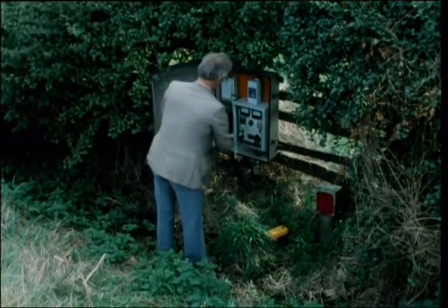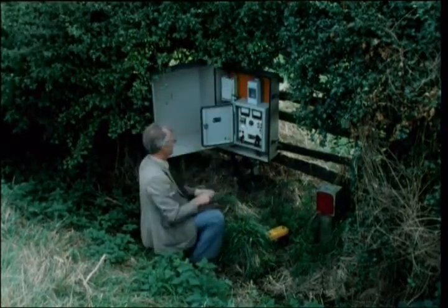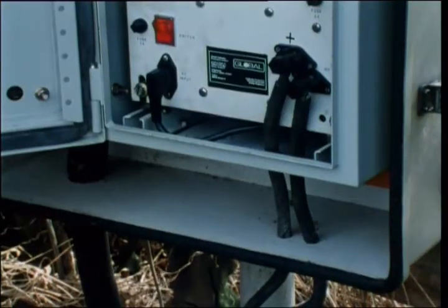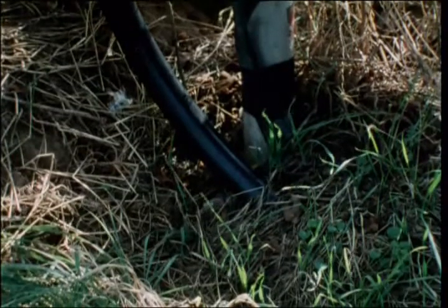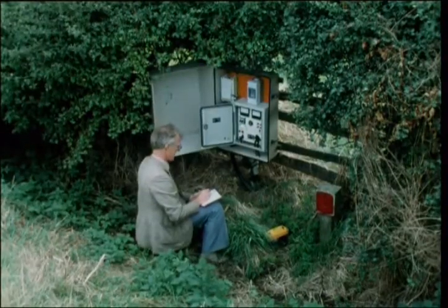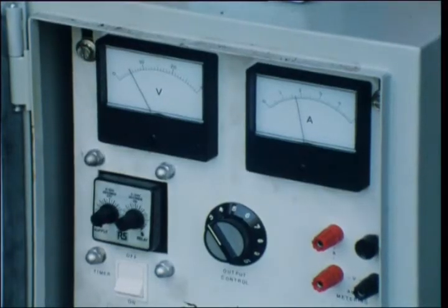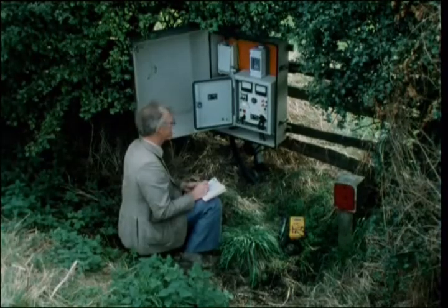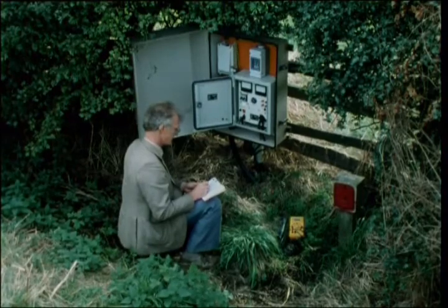An alternative to using sacrificial anodes is to apply a current from a DC rectifier. The protection can be controlled by adjusting the current and checking that the correct electrode potential has been achieved. The advantage is that a pipeline can be protected for several kilometers.